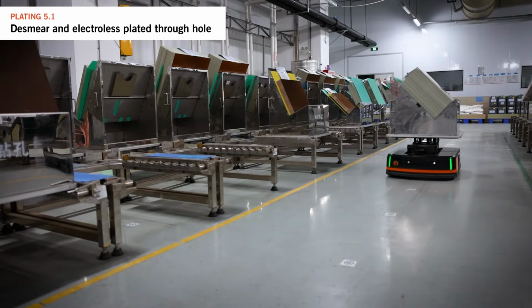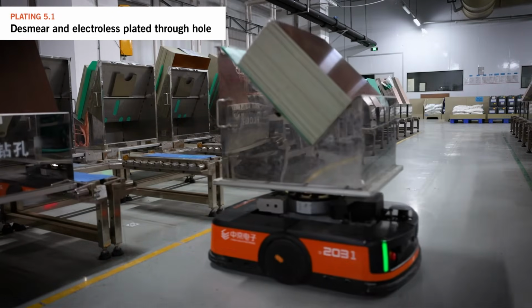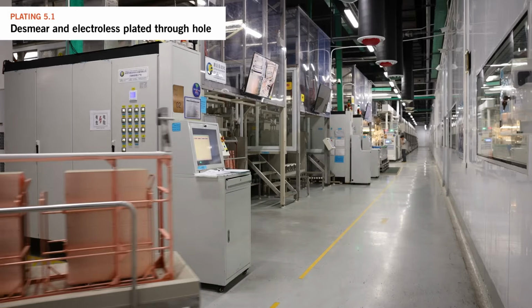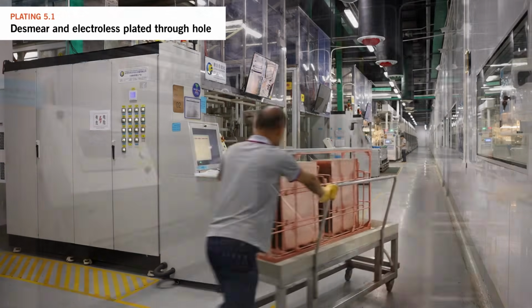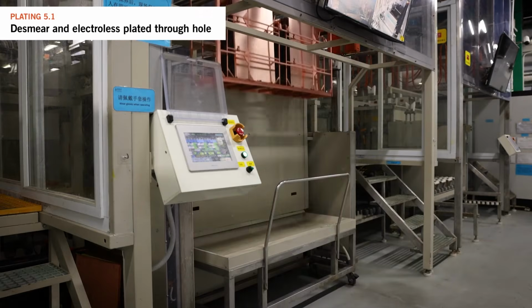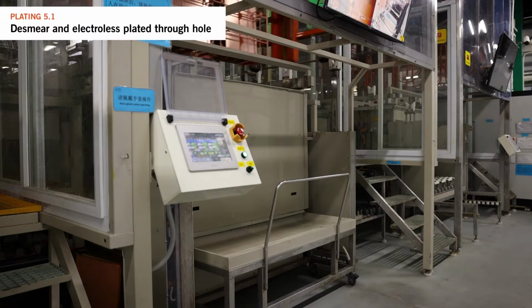The reason we need this step is that we need to plate copper inside the hole. The hole wall is a non-metallic surface, and to plate on a non-metallic surface is hard to do. Electroless is a special plating process that can plate on a non-metallic surface, so this is the first stage before we can plate the desired thickness of finished copper.